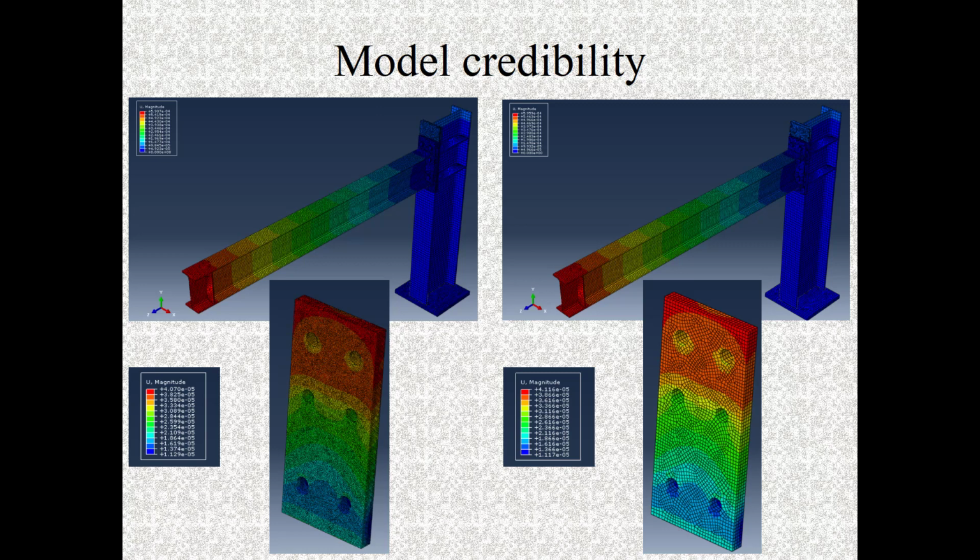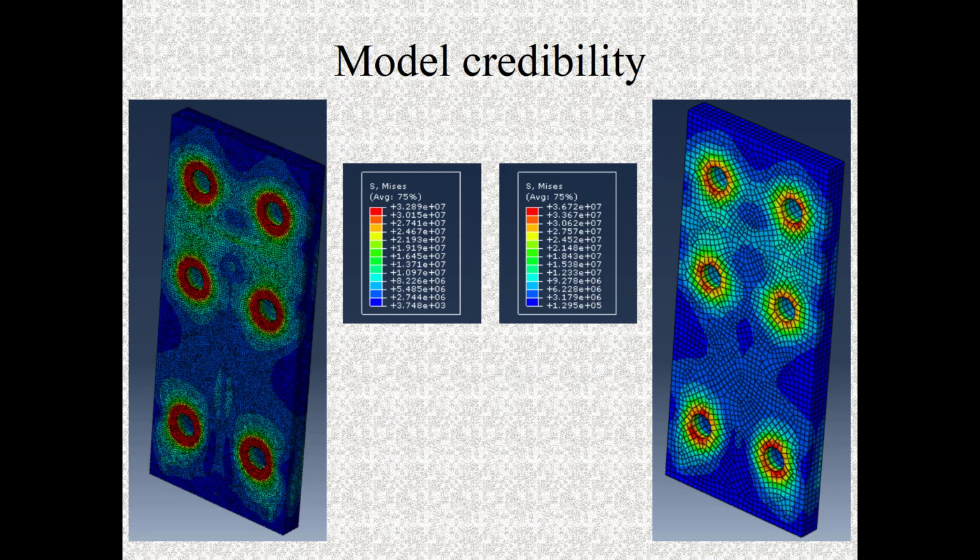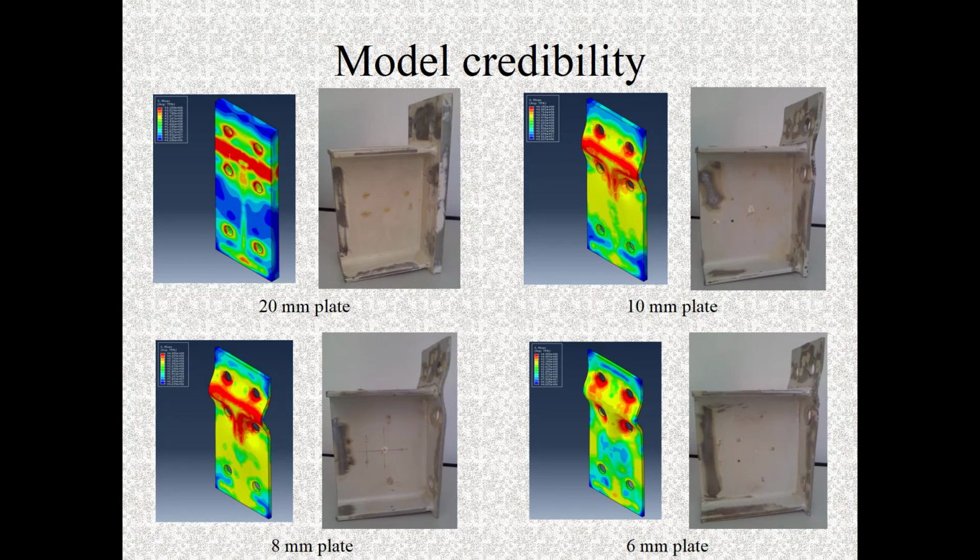However, the difference in the displacements in the end plate amounted to less than 1%. While the difference in the equivalent von Mises stress amounted to about 11.5%, the calculations on the denser mesh yielding the lower values. This is consistent with what may be expected when the displacement-based finite element model is applied. Based on those results, it has been assumed that the lower density mesh would yield the results of sufficient accuracy for the purpose of this analysis.